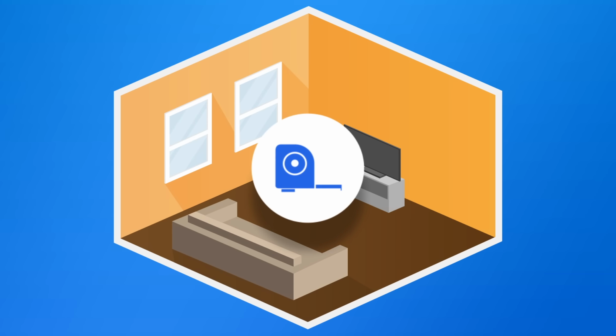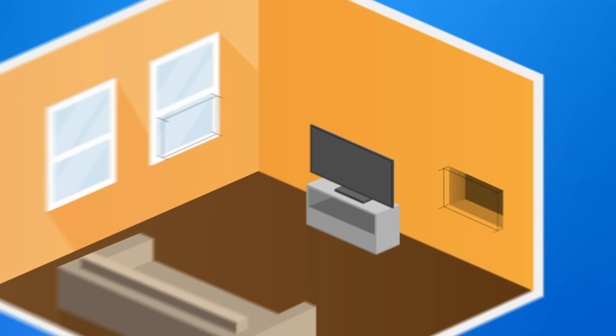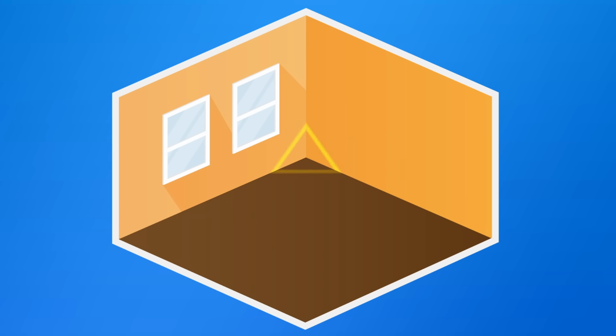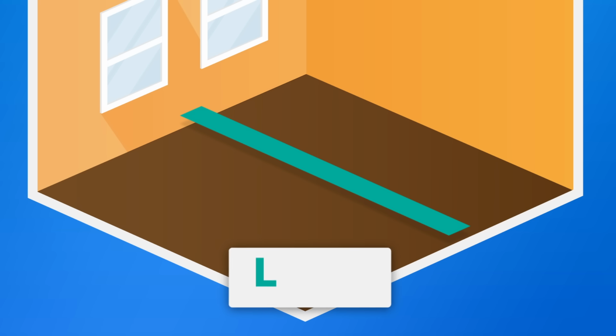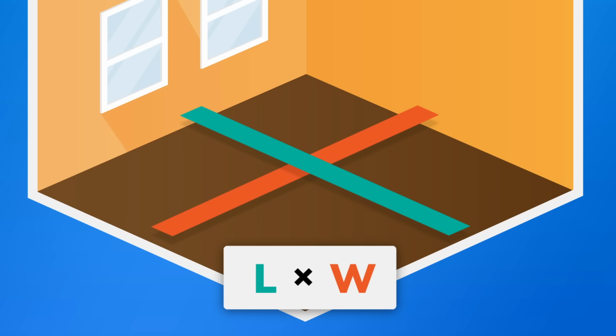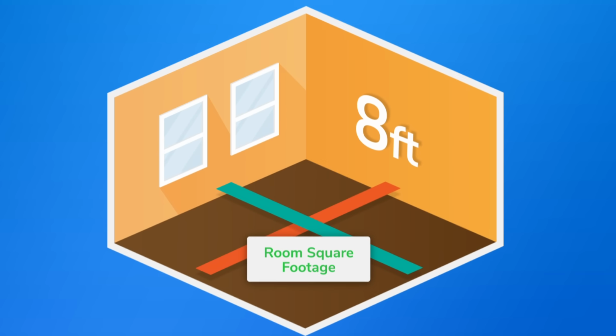The first thing you'll need to know are your measurements. Be sure to measure your window or wall opening, and it helps to have a general idea of the room size you want to cool, taking into consideration ceiling height. The easiest way to check the square footage of the room is to measure the length of the floor and multiply it by the width, and that will give you your room's square footage based on an 8-foot ceiling.